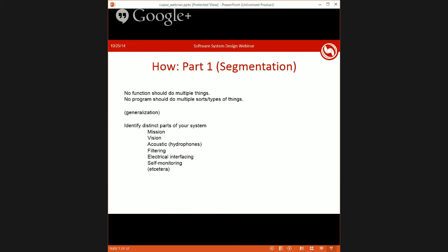You simply call your circumnavigate wire function 5 times, which is a far more general and far easier way to do things, because with that methodology, you can do anything any number of times, and you can combine things in a sort of hierarchical structure. Maybe your whole mission is simply a sequence of task functions, one that hits a buoy, and the next one drives to the wire, and the next one circumnavigates the wire, etc.